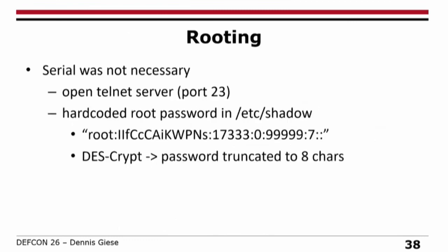Speaking of rooting, actually serial was not necessary, because they have an open telnet port and they have a hard-coded password there. I mean, a hard-coded password is not always bad if you don't know it. So this password is not published yet. And apparently they use the standard example again in this chip. The password is not encrypted with MD5, but with DES crypt. And what DES crypt is doing is it takes your password, cuts it to 8 characters, and uses this password as a key to encrypt zeros.